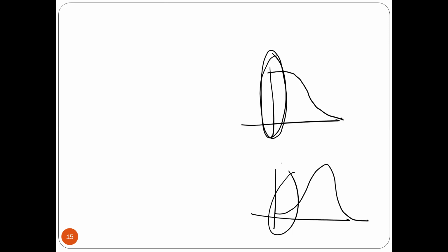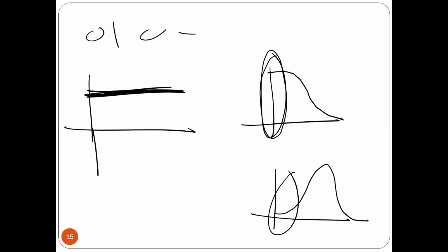But why may we have a DC component? I'm going to tell you why. Again, the problem is that for any pattern, either 1 0 0 0 1 1 1, whatever the pattern is, if the voltage of the signal is going to be high for some time or low for some time, this is going to create a DC component.